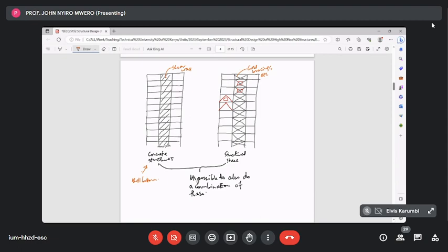You just see them from outside. And you walk in town, you find any of the tall buildings has got this solid reinforced concrete wall all the way from the foundation through the basement to the top. This is a shear wall. It's a lateral load resisting element, and it's put there to carry the shear. And I will demonstrate to you how the building is able to transfer almost 100% of the shear of the lateral load onto this shear wall.